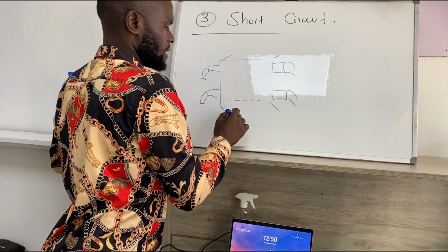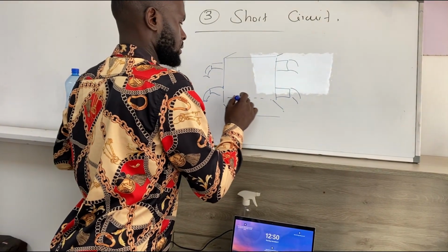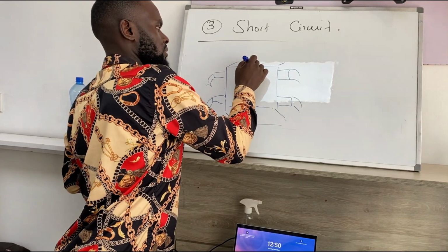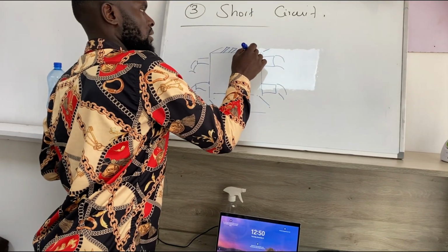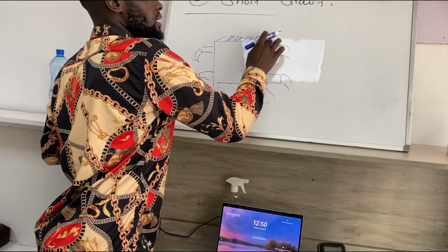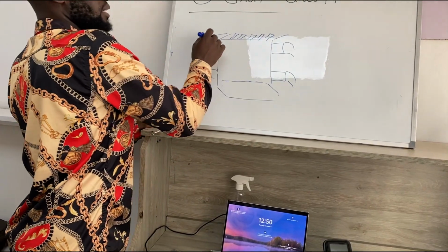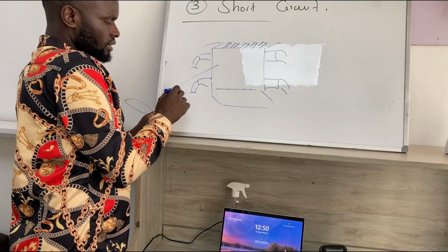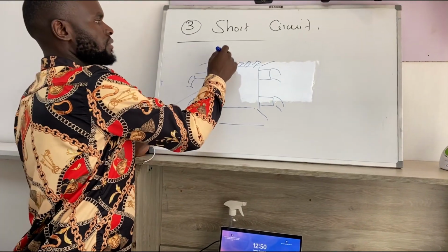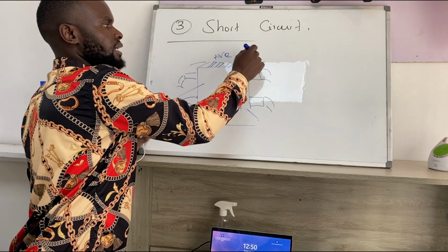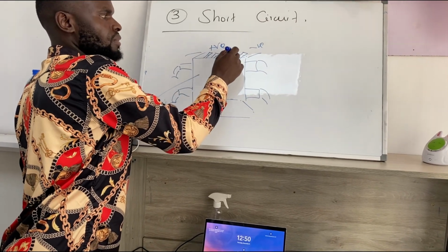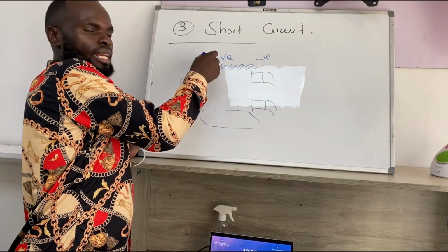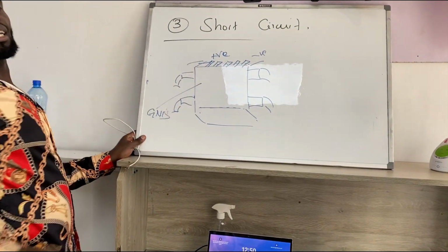Let's assume it's like that. And you'll be having pins here, 1, 2, 3, 4, 5. This farthest end, the very end, this metallic part is GND. It will be grounded. So if you have these ones as the positive and this one as the negative, 1, 2, 3, 4, 5, and while placing the charging port, you happen to link this positive to the nearest ground, negative.